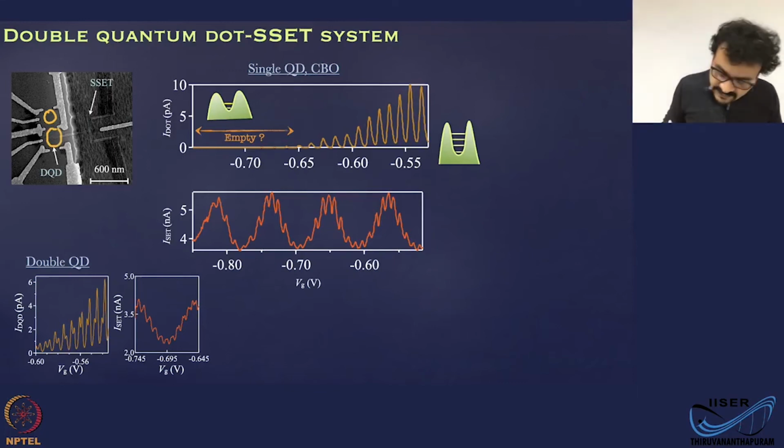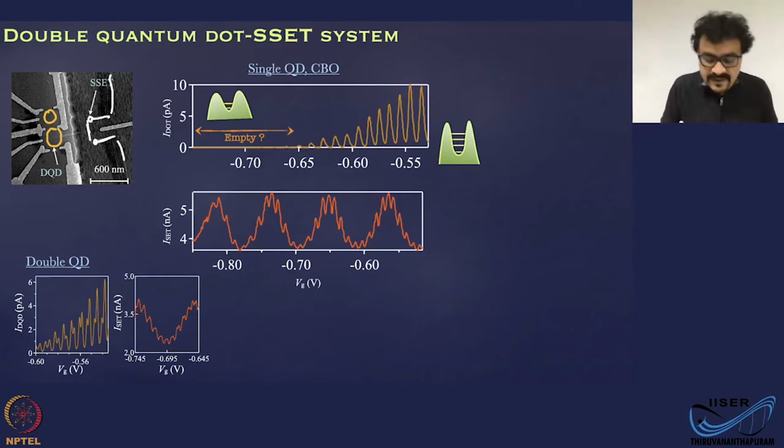Okay, and if you look carefully, you will see a weak image. These are aluminum tunnel junction system. Okay, and this is the gate for the SET, and there is an edge here which makes sure that the electrons in the quantum dot do not escape out here. So the path for electrons is dot 1, dot 2 and goes out, and the sensor extends onto one of the dots